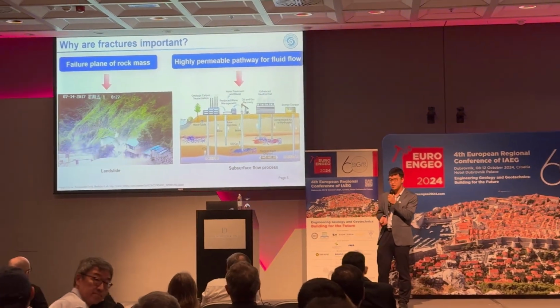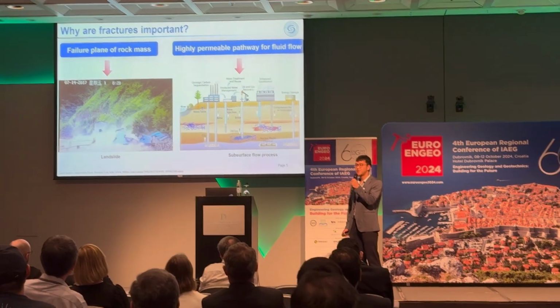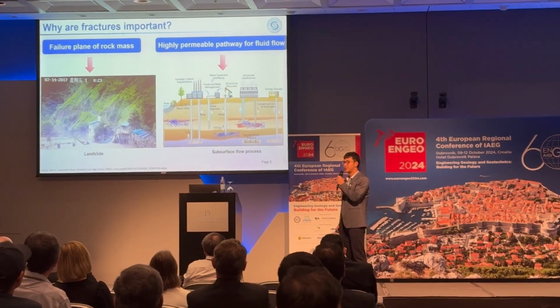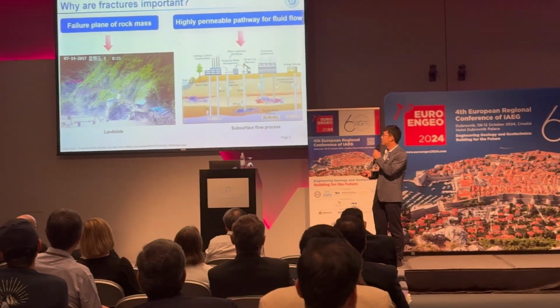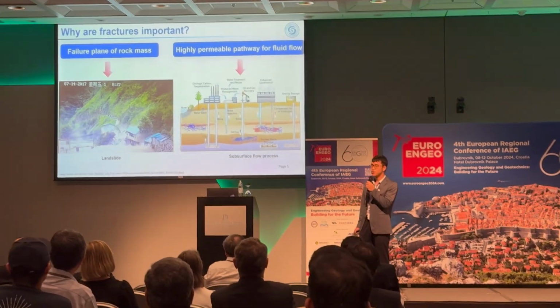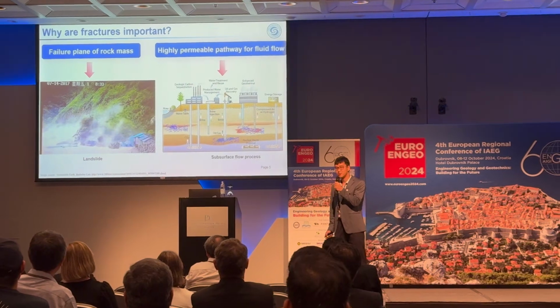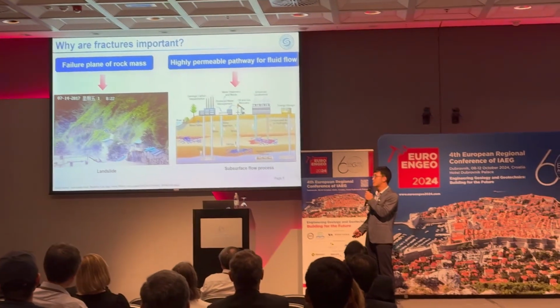So why do we care so much about fractures? That is because fractures are so important. Fractures are the very fundamental feature of the rock mass. On the one hand, they are the failure plane of the rock mass, so they affect or determine the rock stability, which is closely related to many mega constructions and also geohazards, such as landslides or earthquakes.